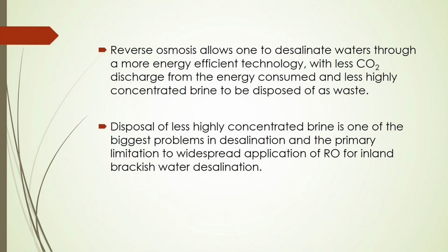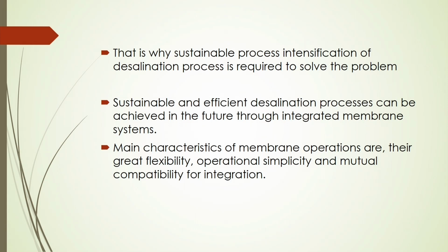In that case, the biggest problem in desalination and the primary limitation to widespread application of RO for inland brackish water desalination is that disposal of the highly concentrated brine is one of the main problems. For that, you have to develop a sustainable process for desalination, and that is why process intensification is coming in, for the analysis of the desalination process by membrane technology to solve this problem.